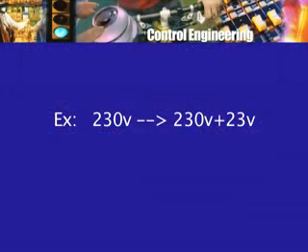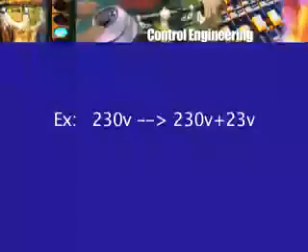So now suppose my Ea were to change from 230 volts by 10%, so by an amount 23, so 230 volts plus 23 volts, my Ea has become 230 plus 23, right. Now what will be my omega m? Now this expression tells you that omega m will change by a certain amount. If omega m was previously 1500 rpm, because that is the way the drive was designed, then now the new omega m will not be 1500, because this part Ea has changed by how much? By 23 volts. And so by how much will the speed change?